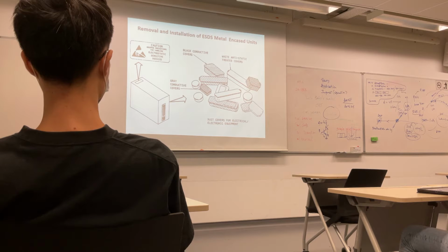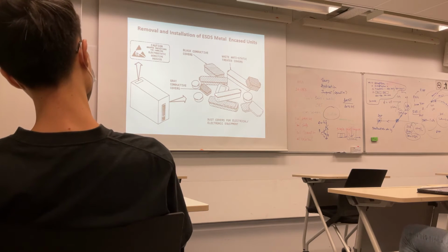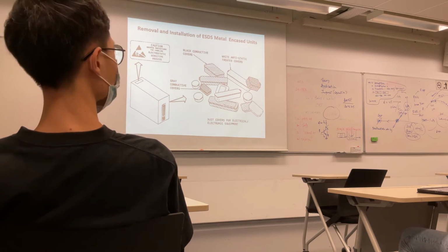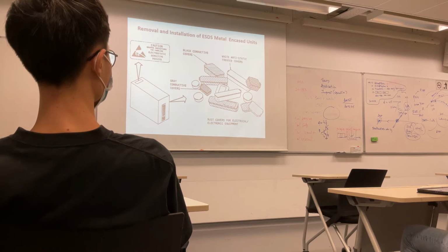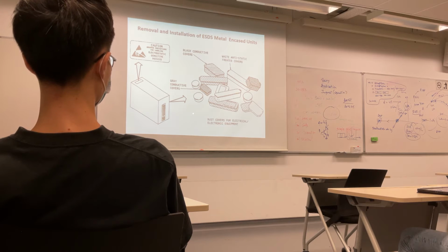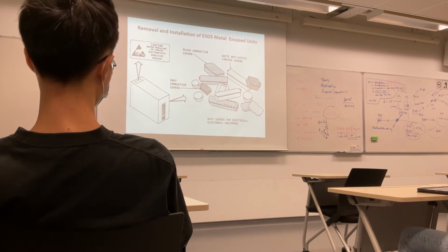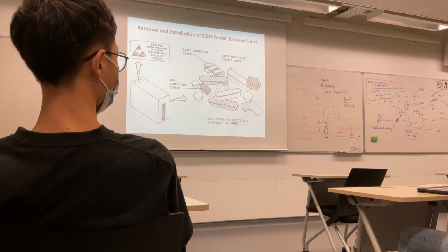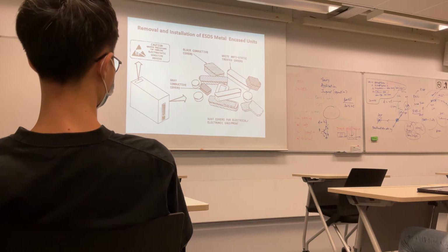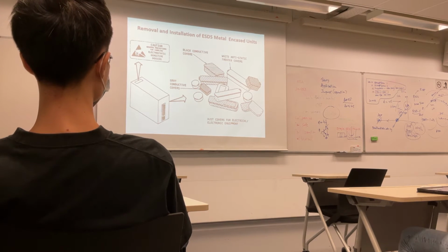And these are the end caps. If you go to an aircraft, they always have an LRU, and behind it you see all the pins, and you have to put one of these caps on. In the past they were always black. Nowadays there are different colors, but in the early days they were carbonized. This is important. We call it a dust cap or dust cover. You never carry an LRU around without making sure it has an end cap. This is the process of ESD protection.